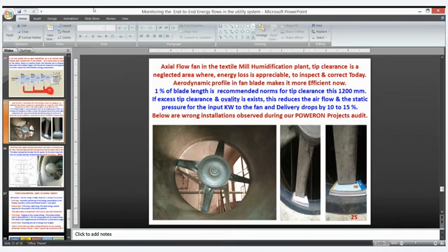They immediately took the step after our audit. They found they were able to restore the flow rate of the blower by almost 15%. Normally the tip clearance is supposed to be around 4 mm only, but here it was 50 mm. I am trying to give the specifics, the minute details of the tip clearance. See, a blade length of 350 mm means almost 1% is only 3.5 mm. Around 4 mm is allowable, but you are keeping around 50 mm.